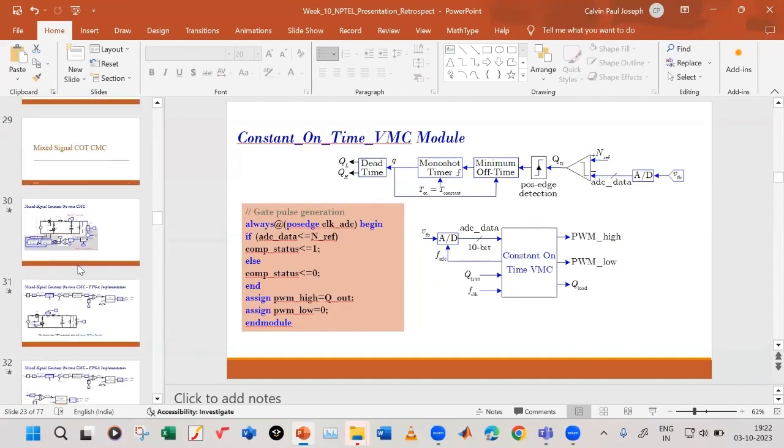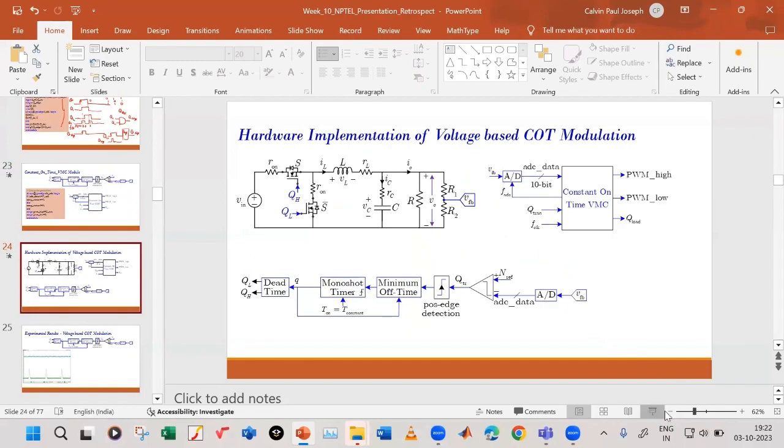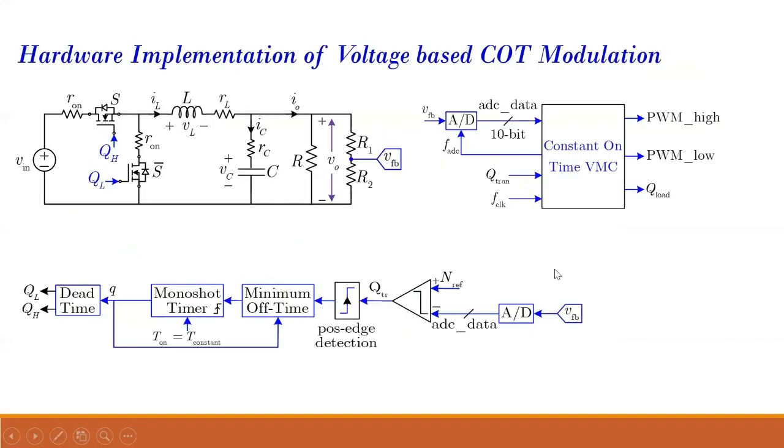In this case, this is my buck converter. QH is your main switch. This is your complementary switch. In the actual conventional buck converter, this is just a diode. So if I do not give S bar 1, if I do not turn it on, then it will just act like a diode. And this is done in light load conditions. During light load conditions, we do that.